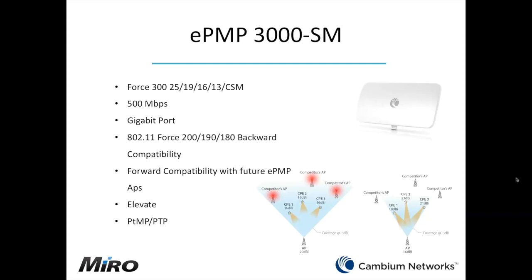Now in the bottom right corner diagram, I've done a little illustration to talk about dBi and the importance of Cambium Networks opening up the various dBi options. In this scenario, it isn't always necessarily that bigger is better. The best practice is to pick a dBi that is best suited for the distances that you're working with.